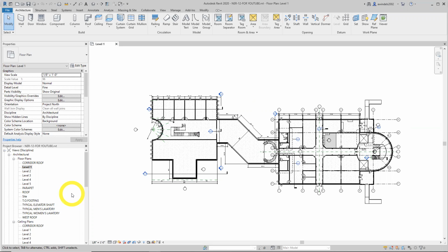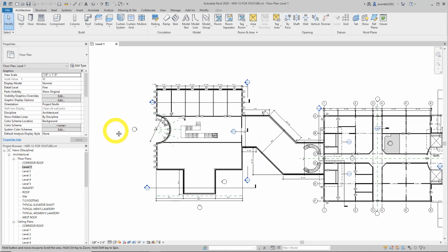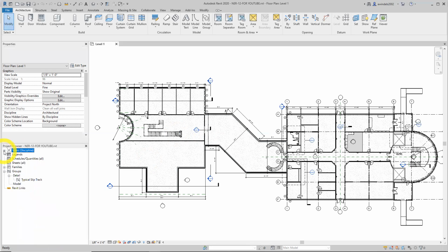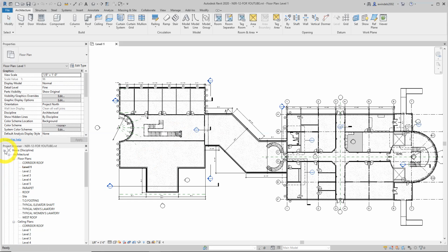Revit is all inclusive with the type of files the book mentions, in that it tries to keep everything in one, every view, everything within one as much as possible. Even in the last chapter, when we brought in AutoCAD details, we brought in a static detail, but we could have linked those details to update in AutoCAD to keep live in Revit. And that's something we'll do later in this course if we have the time. So most of what we're going to get is still going to stay within the project browser. Even when we learn how to do Revit link files, they're still in the bottom here too. So moving on, we'll go to page 616.